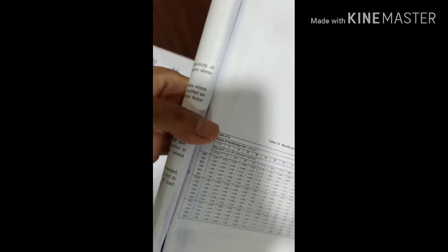So this is table 10. In order to use table 10, the first step is you have to identify the value of the slenderness ratio, which is LE over radius of gyration. From the calculation of slenderness ratio that has been carried out before, we found that